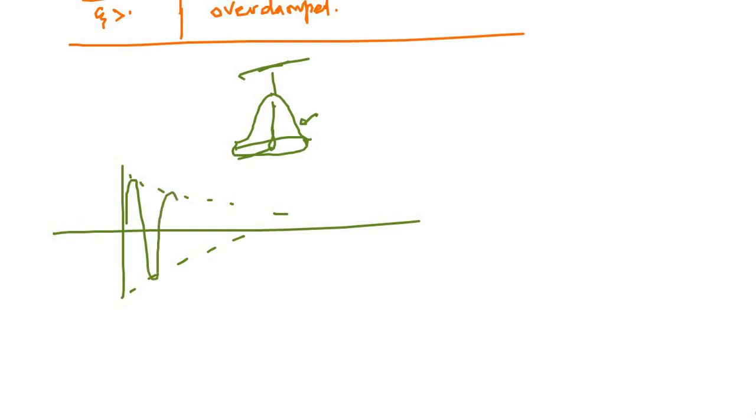Amplitude of oscillation sound அதிகமா இருக்கும். டைம் ஆக சவுண்ட் ஆம்ப்ளிட்யூட் குறைஞ்சுனே போயிடும், கொஞ்ச நேரத்துல 0 ஆயிடும். So whenever you have oscillations and the amplitude of the oscillation is decreasing with respect to time, say some A of t, the amplitude of the oscillations is getting decreased. Now this is called damping. That's called damping. The underdamped systems will produce a similar kind of output, not exactly this.